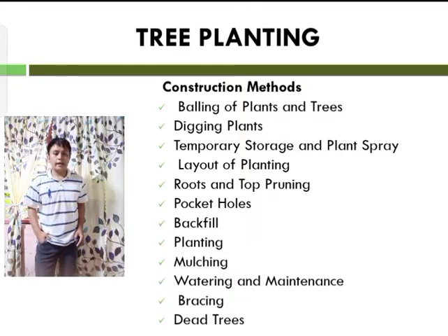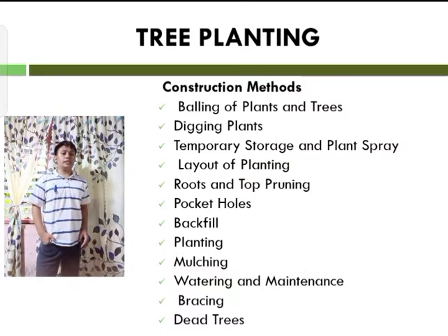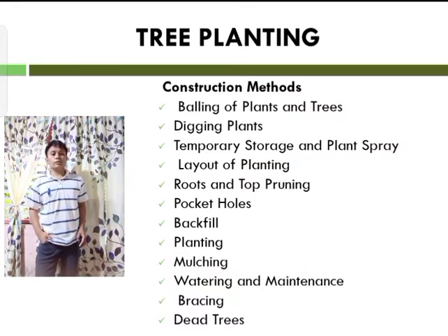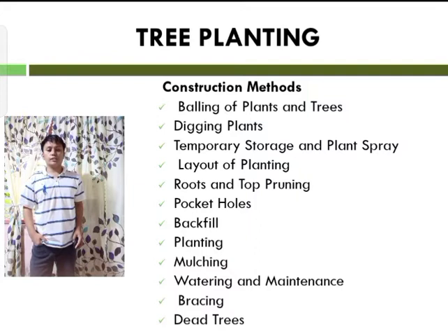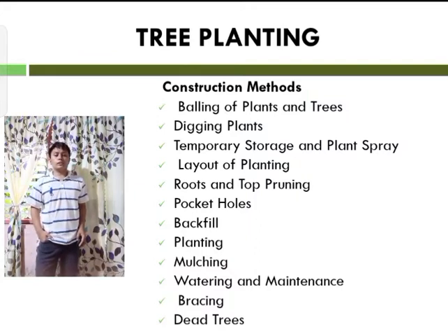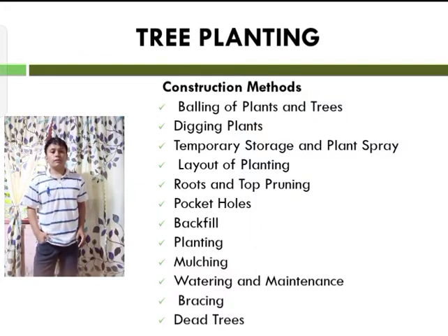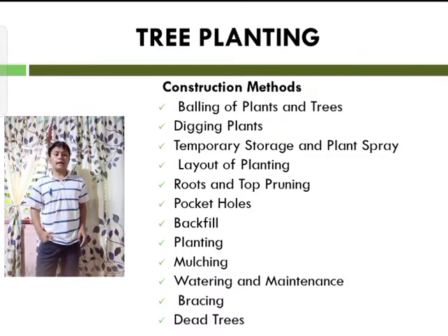So, now we have the watering and maintenance. All plants shall be watered during the planting operations, subject to the direction and approval of the engineer. From time to time during the life of the contract, sufficient water shall be applied so that not only will the topsoil backfill about each plant be kept moist, but also for moisture to extend in surrounding soil.